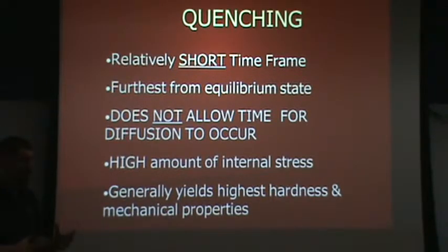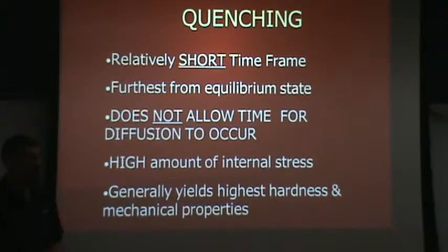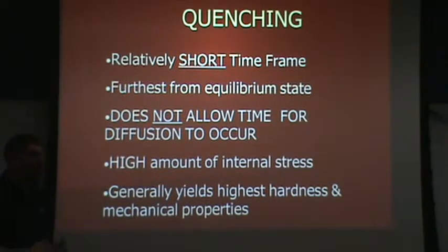Now, that might be a little counterintuitive because we know from our previous discussion that those grades are higher in hardenability than a 4140. They are. However, those grades also are higher in nickel, which is going to improve the toughness in addition to the hardenability. So that could be a viable solution to this customer's problem. That particular solution has a cost implication because you're using something that has nickel as an alloying element. Nickel's one of the more costly alloying elements, so that might not be the first choice. There may be other ways that we can go about looking for a solution for the customer, but it's certainly one that's under consideration.